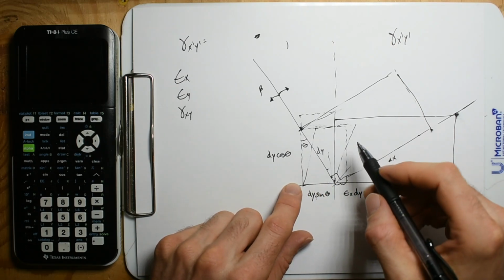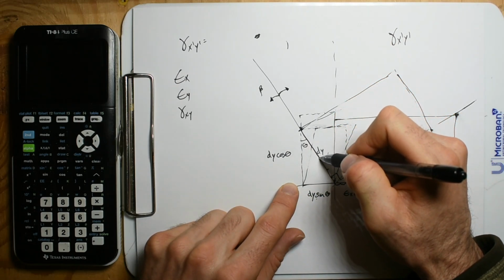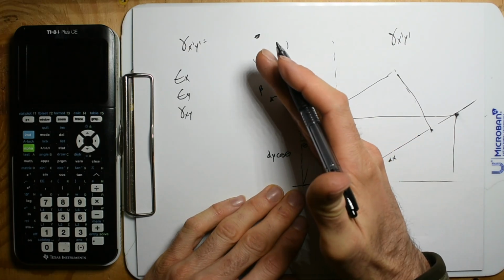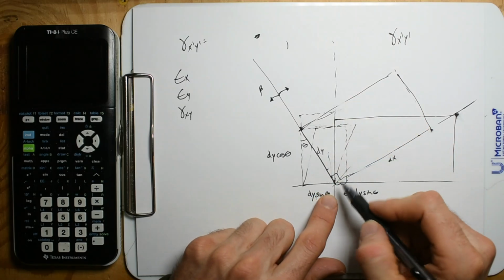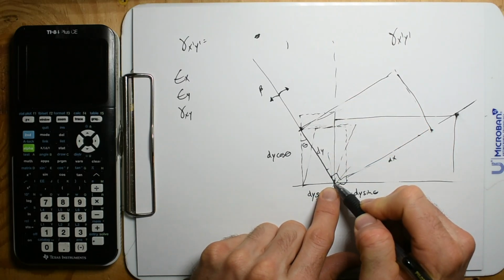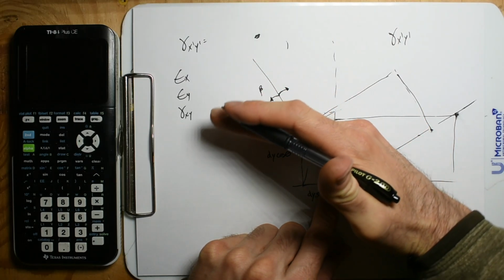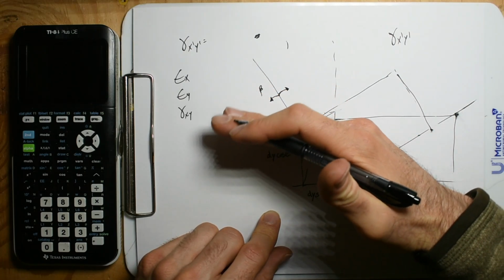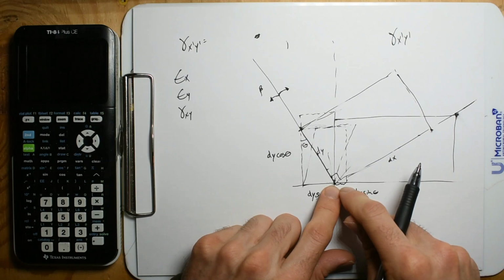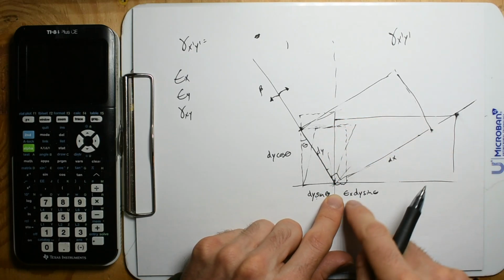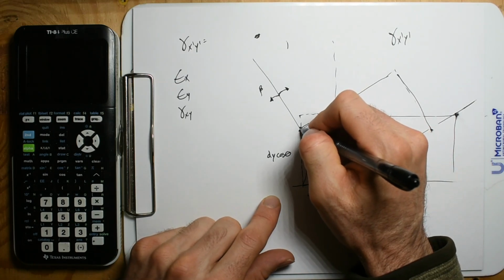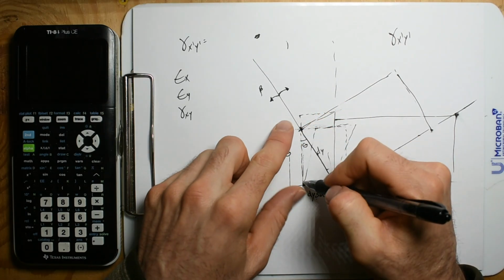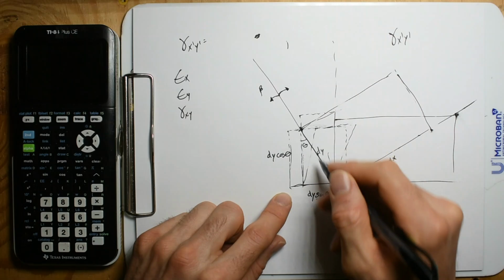Okay, so we are interested in this line changing length, and so that's where you could say that this is rotating. It's kind of nice to fix this point. It doesn't matter though. If this line rotates, even if it rotates about the center, this line is changing angle. And so this could be useful. Even though we have positive shear strain in the x, that's the same thing as making it positive this way. You know what I mean? If this initial rectangle bulges out this way, that's going to be the same.